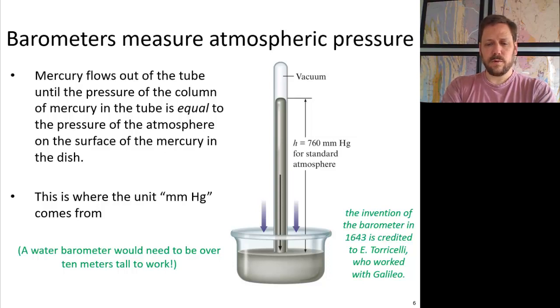And that's because in order for that to happen, the water leaving the test tube would have to displace the water in the tub upwards, but atmospheric pressure is pressing down and preventing that from happening. Now, if you had a sufficiently high tube of water, it would have to be over 10 meters tall for this to work, but you would in fact see the water begin to fall away from the top of the tube. That is a measure of atmospheric pressure. Now, with mercury, it's such an incredibly dense liquid that that happens in less than a meter, so only 760 millimeters at standard atmospheric pressure.